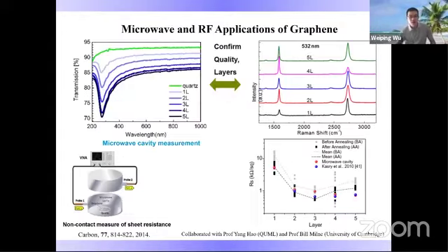We tested these RF cavities using optical absorption techniques as well as Raman spectroscopy to confirm the successful formation of bilayer, 3-layer, 4-layer, and 5-layer graphene. In addition, we determined their sheet resistance and showed a very interesting trend of reduction in sheet resistance as the layers of graphene increased. This offers us a new approach to build low resistance electronic devices, as well as high performance radio frequency devices.